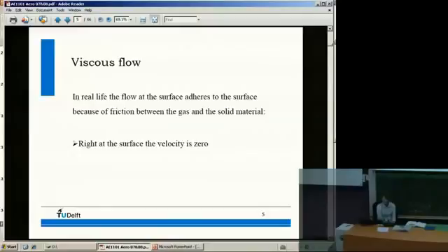Okay, so viscous flows, always viscosity plays a role, depends a bit. In liquids and for small objects it's much more dominant. So airflow around very small objects, air around a fruit fly, is as if a bird tries to swim through oil. So you can have certain numbers that relate how you can compare flows, but for each object you have a friction somewhere. For aircraft flying through air at high speeds, the area where friction has an effect is usually only in the boundary layer.